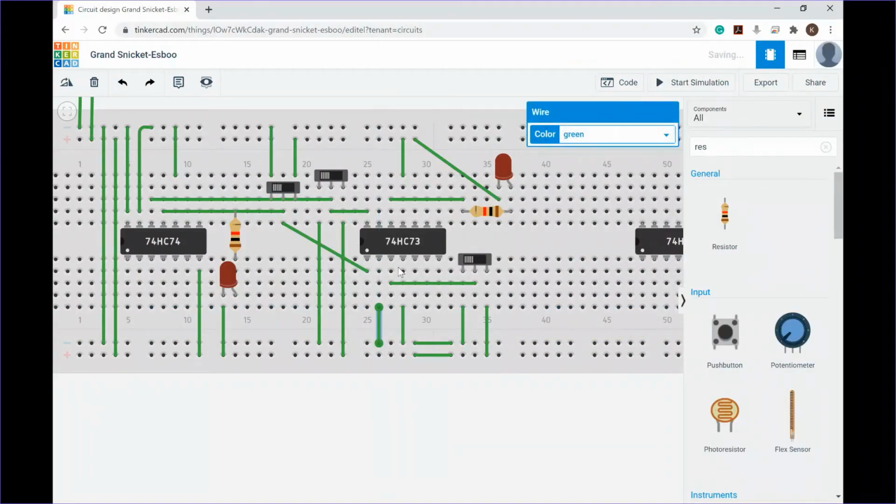the reset. Okay, so now my J is at 0, so if I put this here means I go to 0. Then my K is at 1. If I give a clock pulse, the LED will remain at 0, right? So if I give my K to 1, my J to 1, this is my J. My J is connected to this one. So I use my J to 1, then my K to 0. Okay, it should light on, right? Right, it's light on. I give the clock pulse, it will light on.